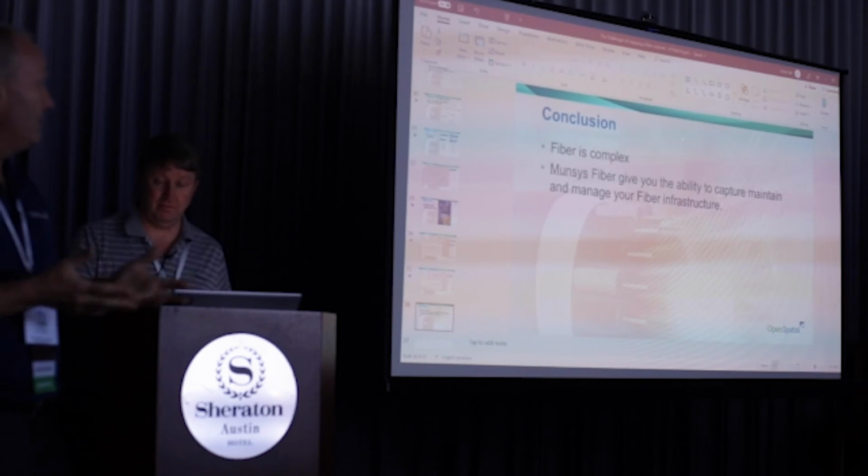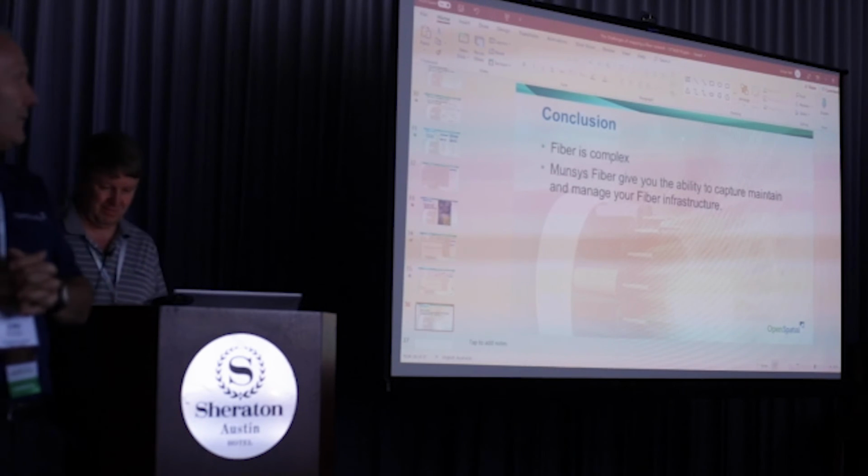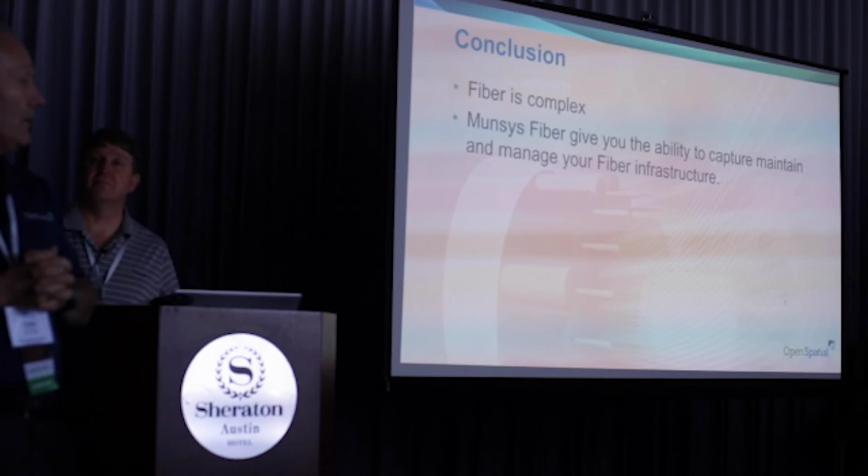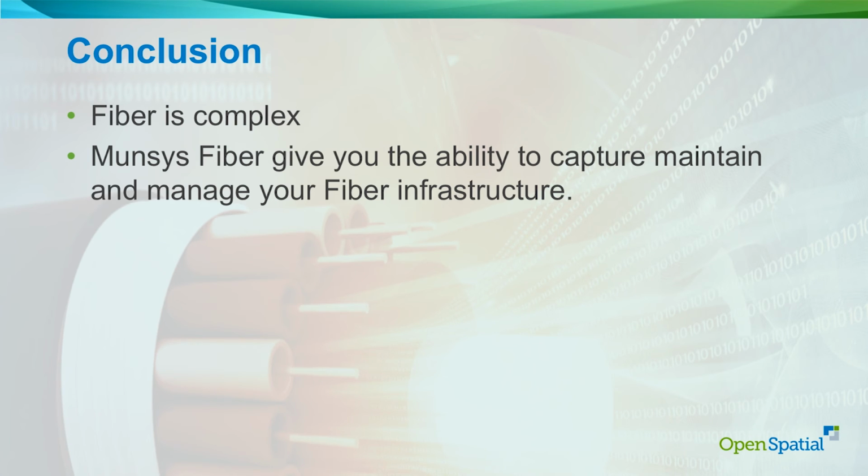All right. Well, if I had to rank them by complexity, water networks, aside from being a pressure network, would probably be the easiest to map because it's just dots and lines. You've got to make it interconnect so it's a pressure and the stuff can flow in the other direction. The next level up would be gravity networks, which are also just dots and lines. A node or join point in the network doesn't have splicing going on. It's going in this direction and it connects, so it's pretty easy. All you have to deal with is the invert elevations and flow direction. So that one's a little harder than water.